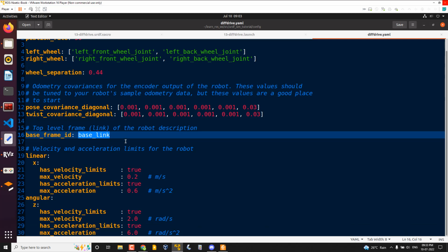Okay, odometry means the local estimate of the robot position. Local estimate means, from the starting point of the robot, where is the robot? Maybe in the x direction it's 1 meter from the starting point, y will be like 0.5, and theta, the orientation, will be another value.